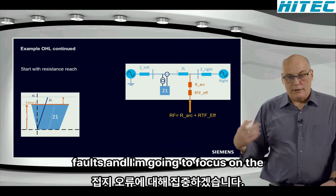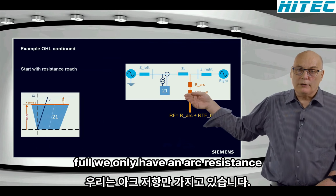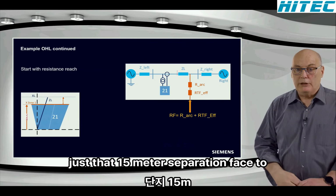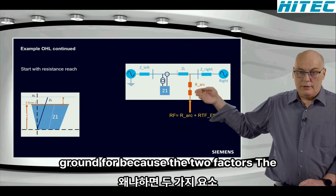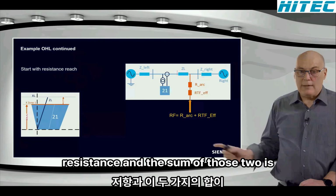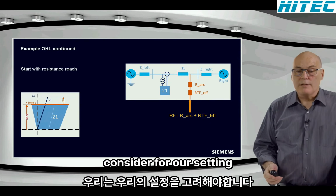And for the ground faults, and I'm going to focus on the ground fault, remember for the phase-to-phase fault we only have an arc resistance. There's obviously no tower footing resistance. It's just that 12 meter separation phase-to-phase that is relevant, not the tower footing resistance. But for the phase-to-ground fault, it consists of two factors, the arc and also the tower footing resistance. And the sum of those two is the effective RF that we need to consider for our setting.